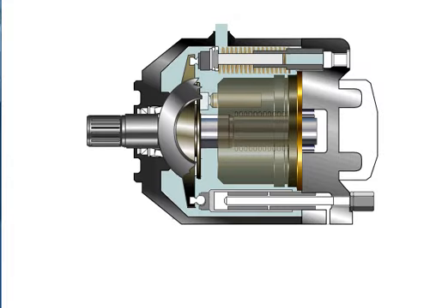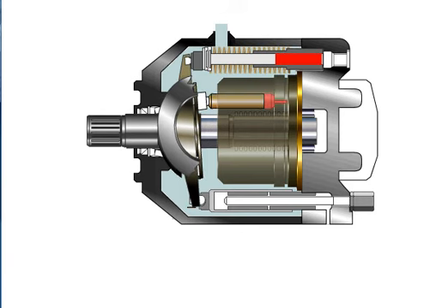In this learning lab, axial piston pumps convert rotary motion of an input shaft to an axial reciprocating motion of the pistons. This is accomplished by a swash plate that is either fixed or variable in its degree of angle. With the swash plate vertical, no displacement occurs because there is no reciprocating motion. As the swash plate increases in angle, the piston moves in and out of the barrel as it follows the angle of the swash plate.